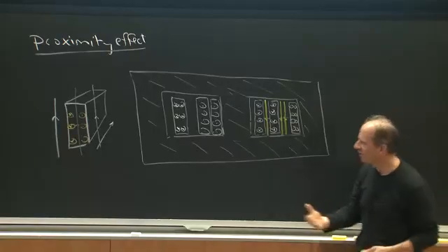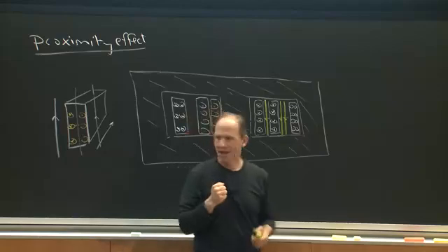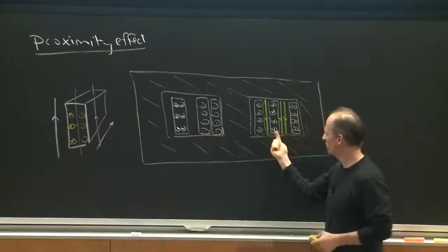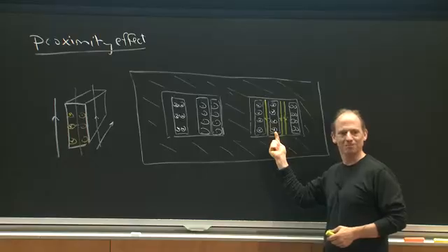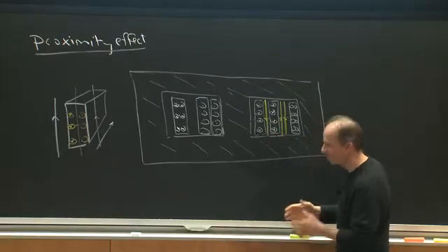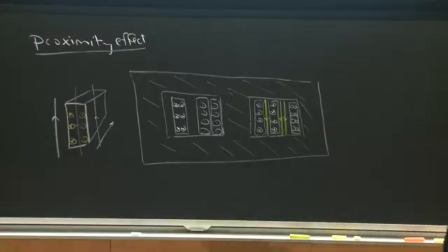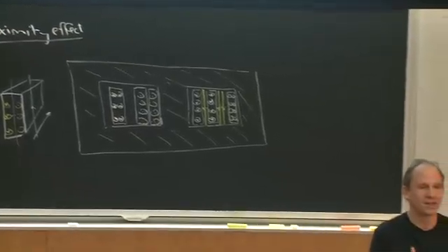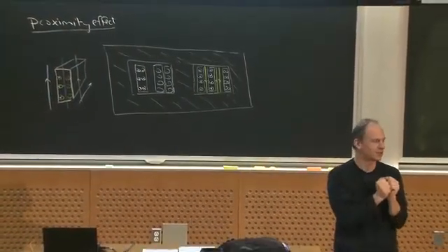And what happens is I've got this effect where I'm imposing fields on my conductor, and I'm going to get eddy currents in this second layer that's going to cause loss. And the problem with that is, especially if I have very many layers of winding and very high AC current components, the induced loss gets reflected, and the way it looks electrically is a much higher AC resistance to the winding.